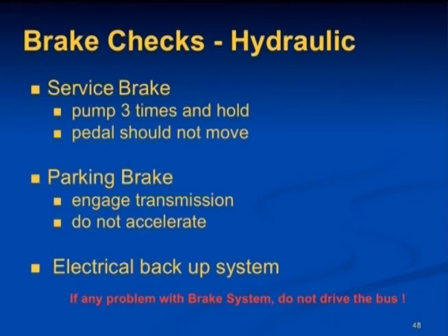Apply the service brake firmly. The bus should stop in a straight line without skidding, swerving, or pulling to one side. The brake shouldn't grab or lock or make excessive noise, and report any excessive pedal pressure or abnormal or unusual braking behavior. If the condition prevents safe braking, do not operate the bus until the condition has been repaired. Check any gauges that you have on your brakes periodically.